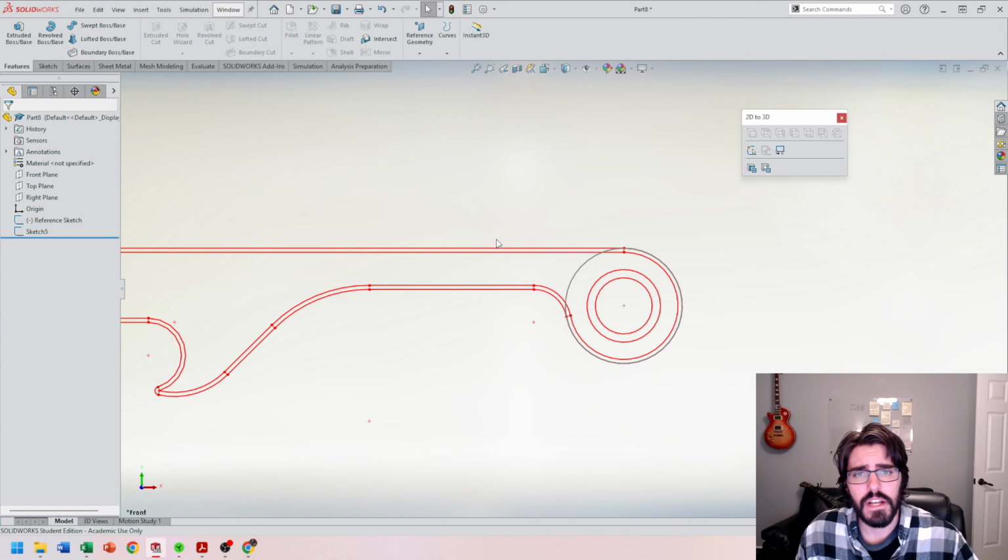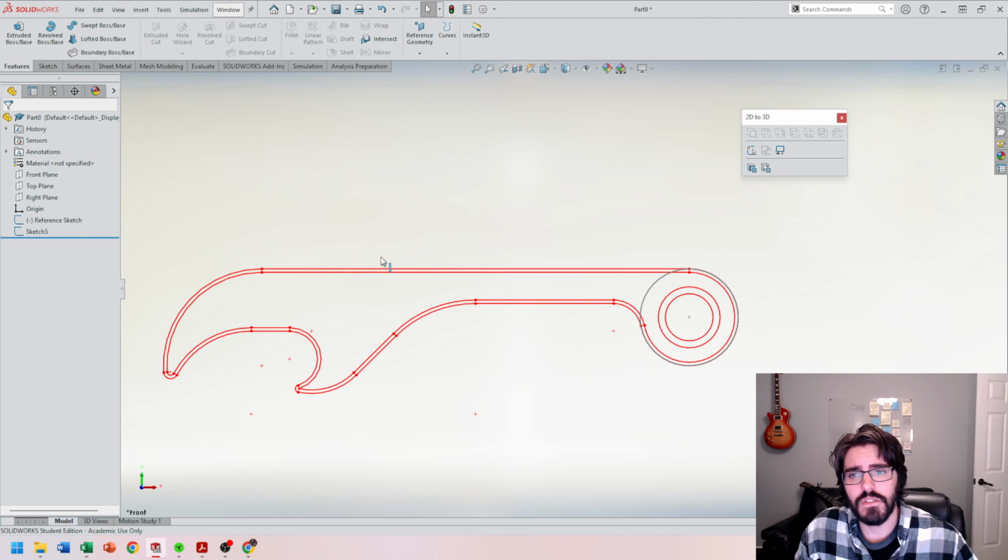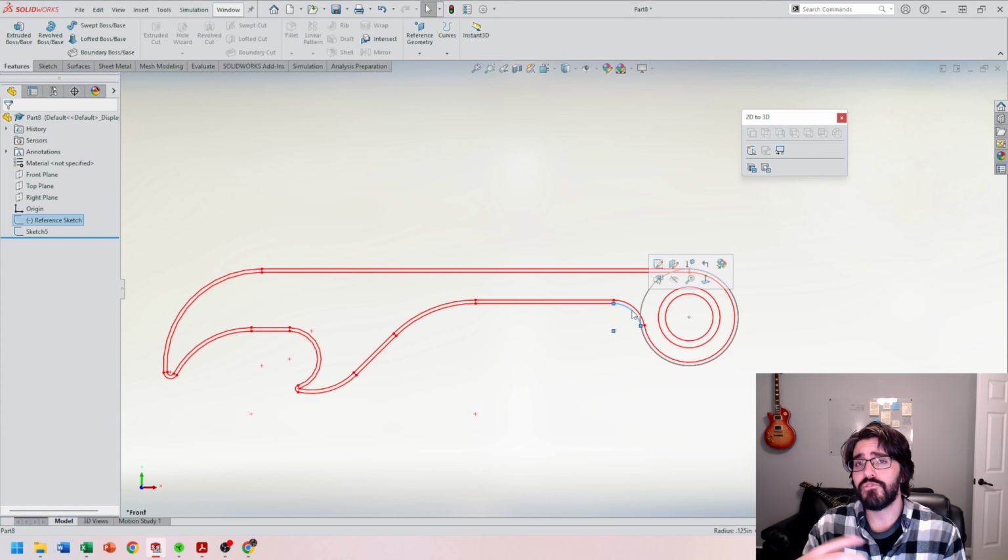And while this is on, I want to reference this in such a way that I know what geometry I'm going to create next. So I'm going to probably draw a line that's horizontal to the left. Then I'm going to create an arc, another arc, another arc, a straight line, an arc, arc, arc, and then an angled line, arc into a straight line, and then into an arc. Now I'm actually going to make this arc here and this arc here 2 intersection points, and I'll fill them in with a sketch fillet later because I think it'll be a little bit easier for us to process.